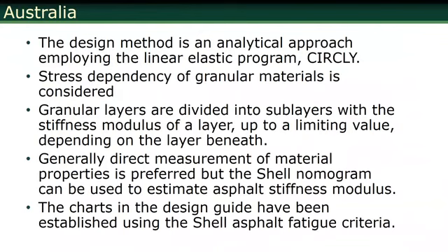Design method is an analytical approach employing a linear elastic program, CIRCLY. So this is the pavement ME software equivalent in Australia. It's not the same, it's a little bit simpler, but it's different. One important improvement over pavement ME is stress dependence of the granular material is considered. So in pavement ME, you can also consider this, but CIRCLY is pretty good at this also. And granular layers are divided into sub-layers with stiffness modulus of a layer up to a limiting value.